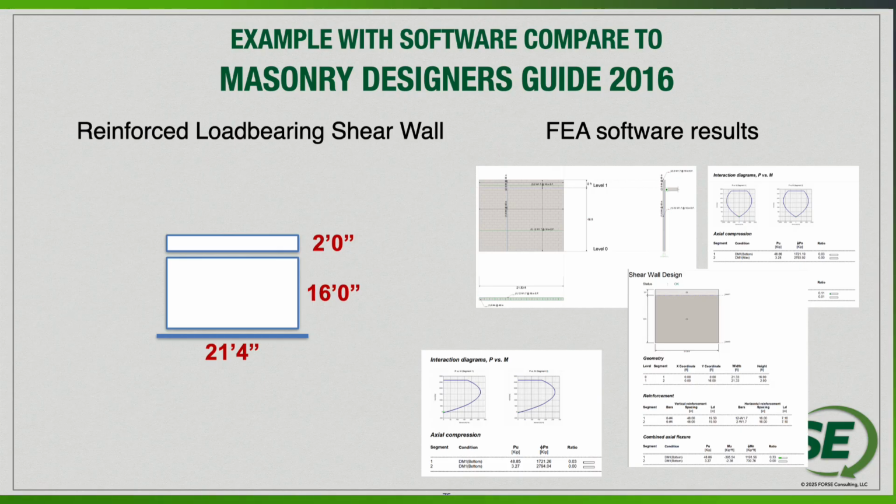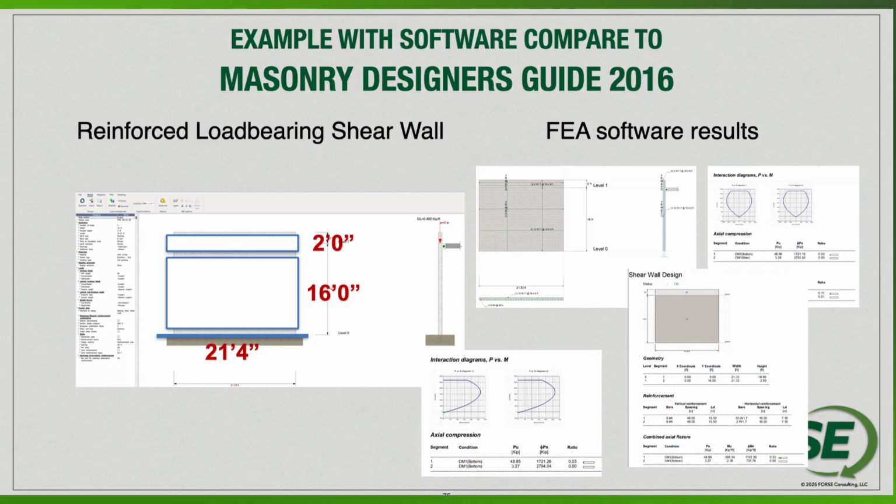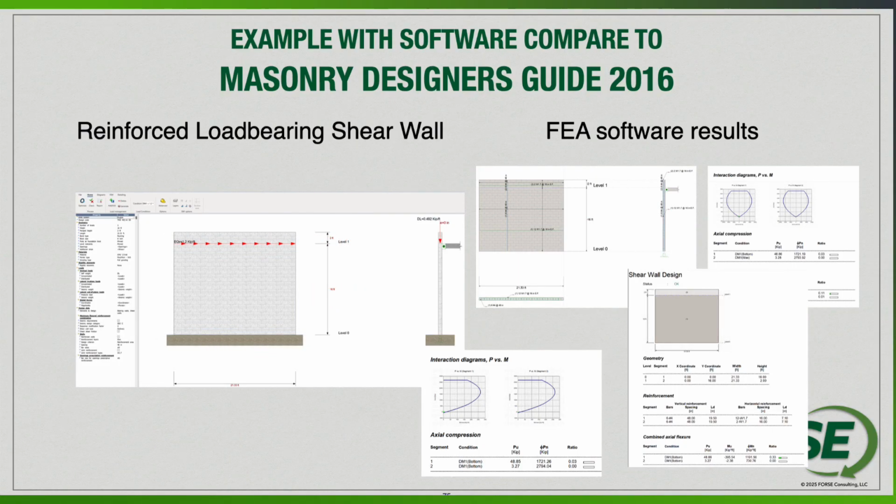So certainly we can look at the design. We can do the design checks by hand. We can also go into software. We can see very similar axial to moment curves that are going to be created for the design and do a nice little comparison between our hand calcs and what we have in here from finite element analysis.